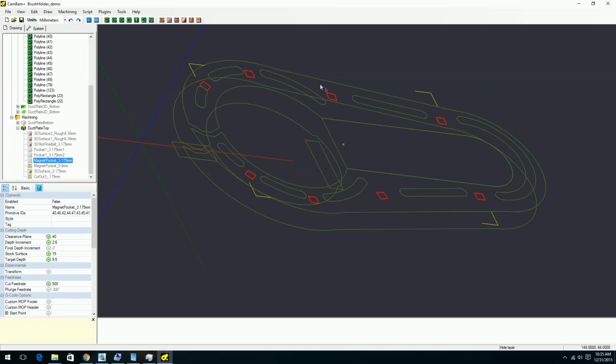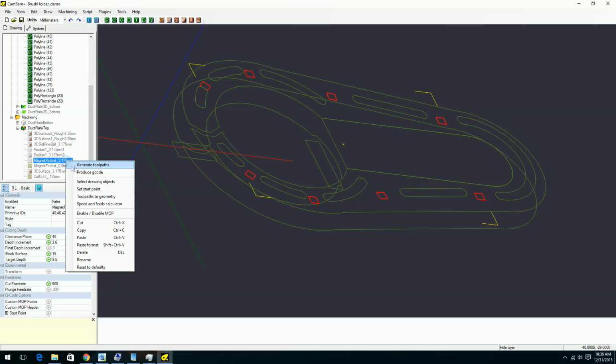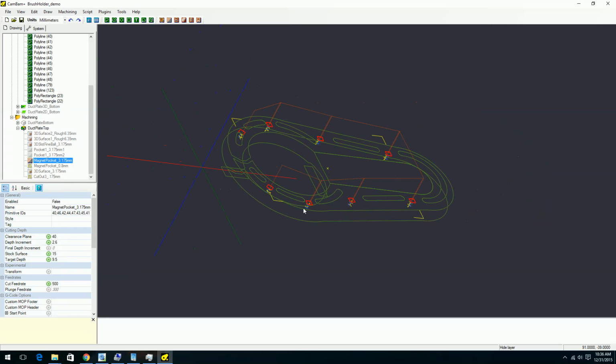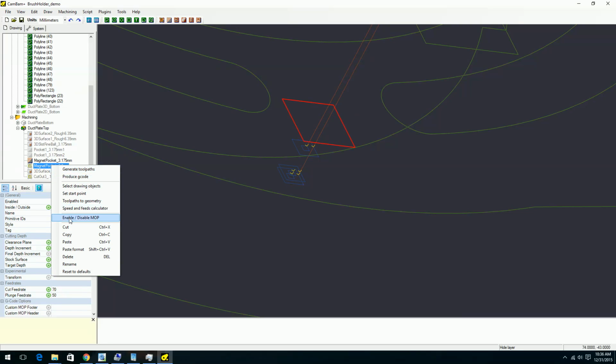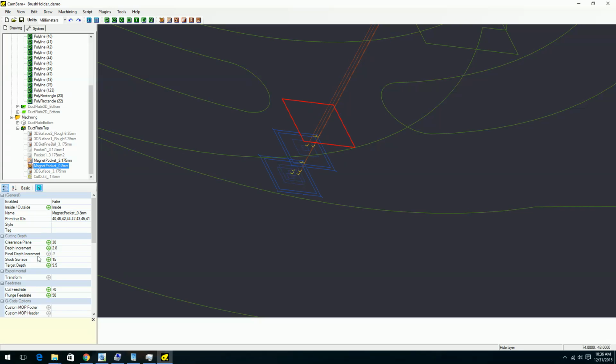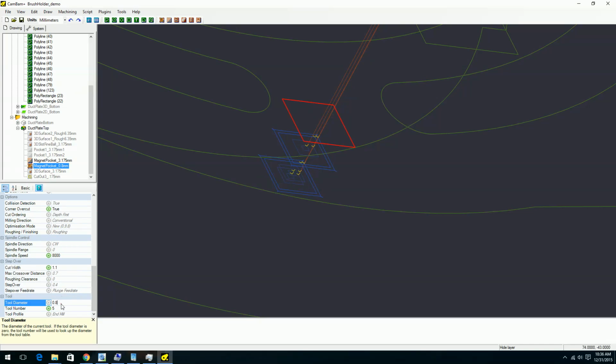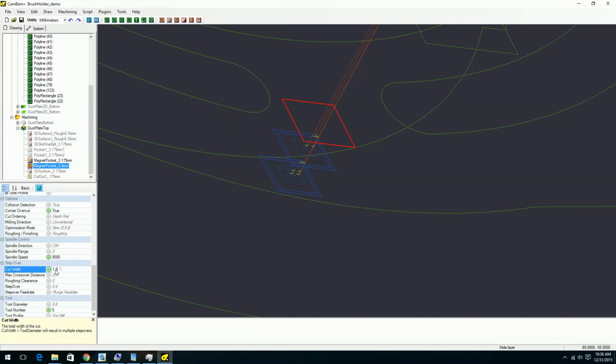Then this again is for the magnet holes, again with a 3.175mm bit, 1/8 of an inch. And then I'll finalize that again with a very fine bit, 0.8mm, with a very slow cutting again. And I have a cut width of 1.1mm here, so that will give me a very nice line. Final end result will be very nice.